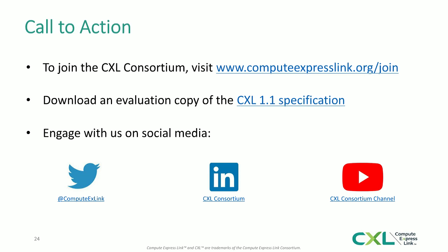Okay, this will be the last question. Can two sockets which are not connected via a coherent interconnect use the CXL metadata value to manage coherence for CXL connected memories? So that's not really the intent here. CXL supports asymmetric coherence protocols, and you need to still have a coherency agent on the CPU itself. So the memory device itself is not intended to be a coherency agent.